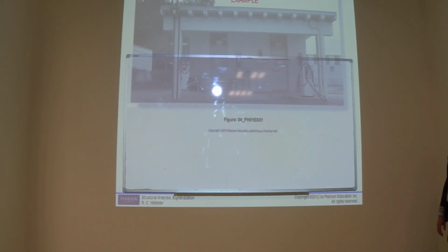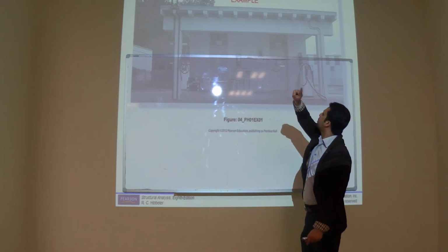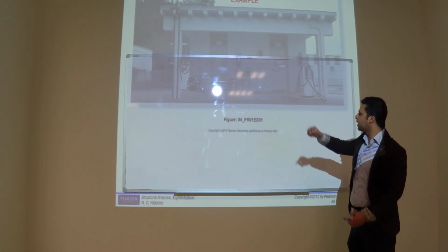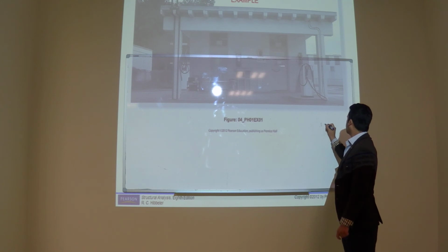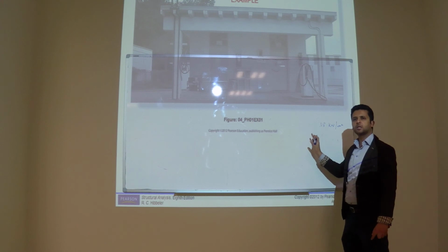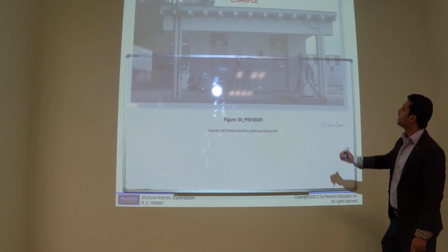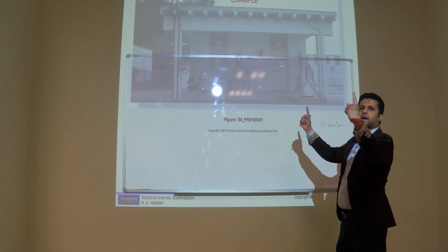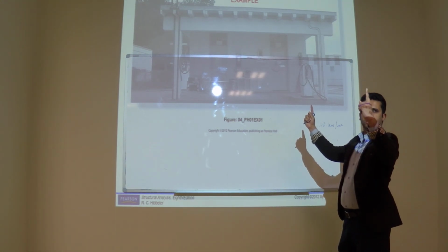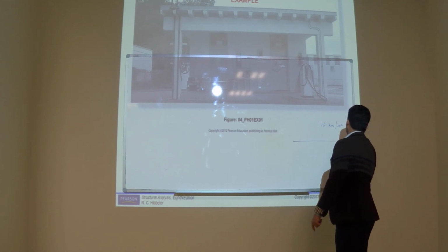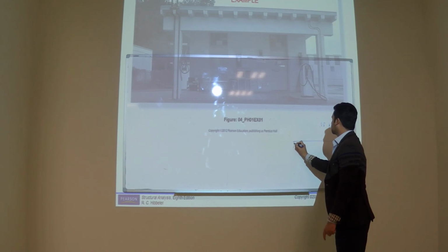First, let's talk about the joist. These joists are running perpendicular. 1.8 kilonewton per square meter is the roof load. It's already multiplied by the thickness, the whole roof. And this is an 8 meter span. I'm going to show it like this. So we have 8 meter beams, simply supported.